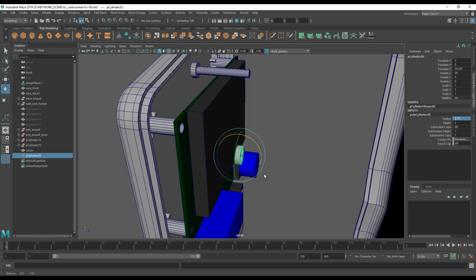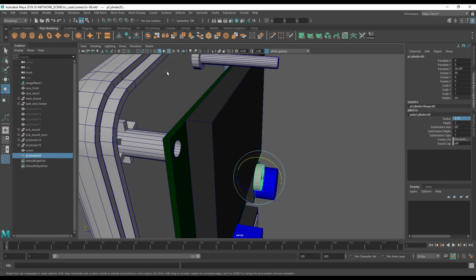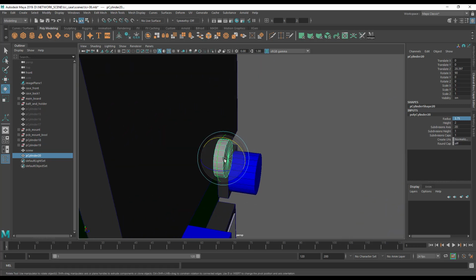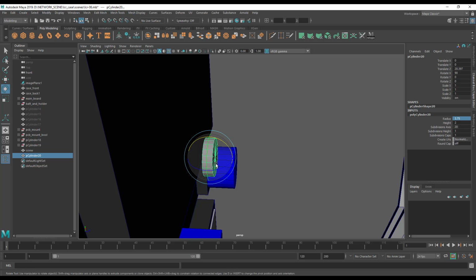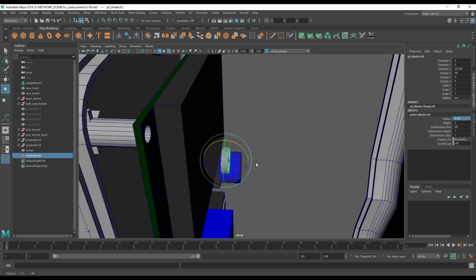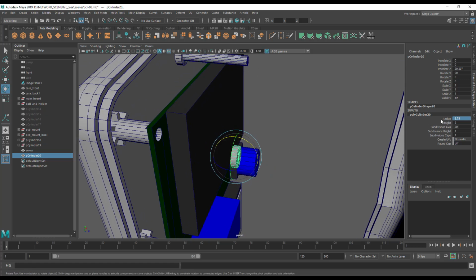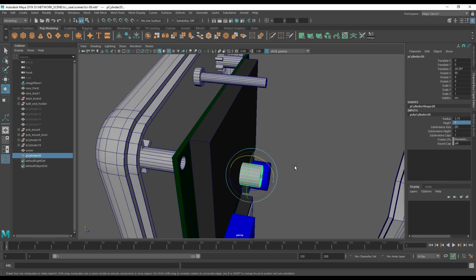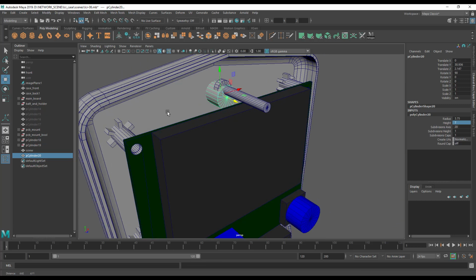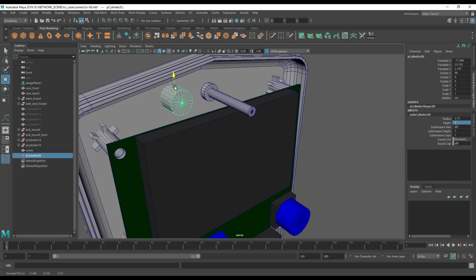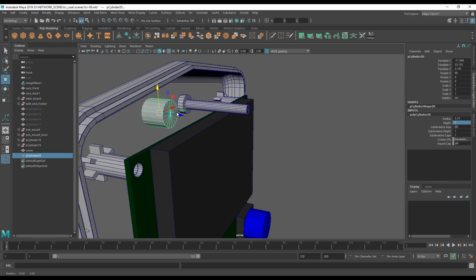Now the head will protrude 5mm into this nub, 7mm in total, which means we want some excess plastic on the top of this. And as we've gone for a 2mm thickness all around, I'm going to go for 2mm again, and I'm going to make this 7mm. So let's make it a height of 7mm. So basically on the back side of our case, whoops, that was the wrong axis, on the back side of our case here will be a 7mm nub in which the screw head will sit.